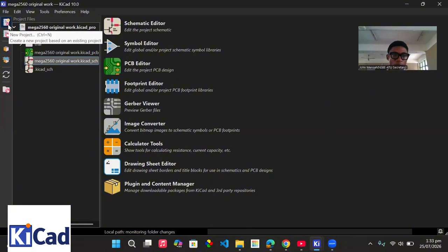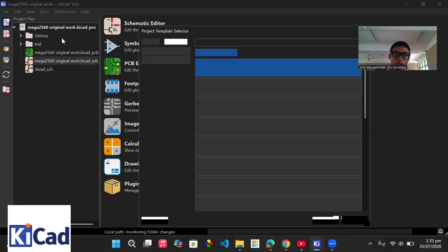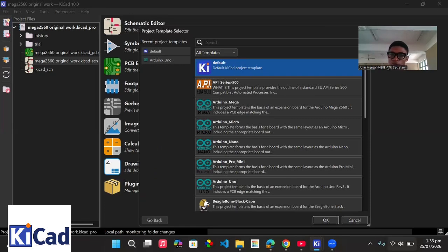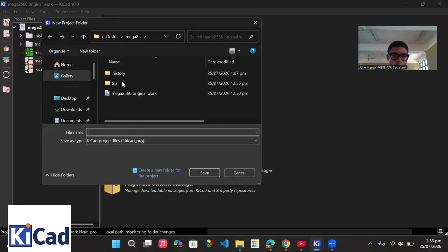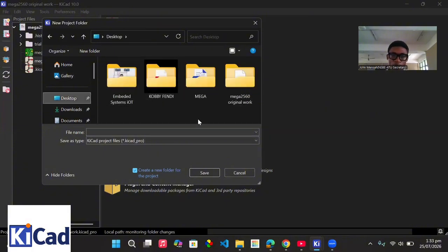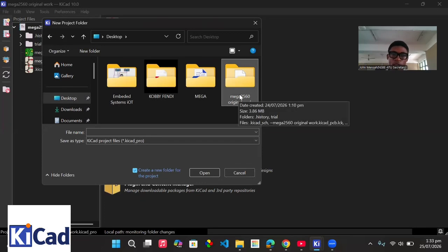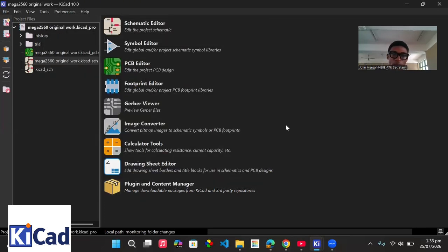So you quickly come here, you can see it is written new project here. You click on it and then you leave it on default. You click on OK. Then also you have to create a folder for your project. I already have my folder created. You create a folder, you name it to your preference, and then you save it. So that is how you can quickly create a new PCB, a new KICAD project file.